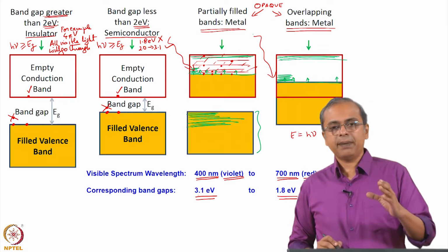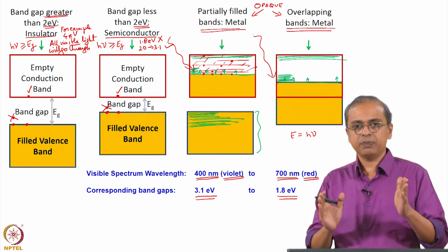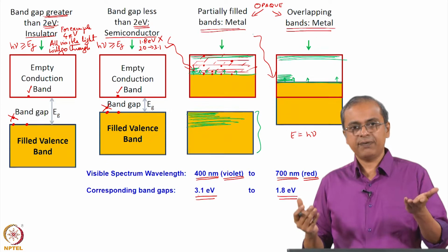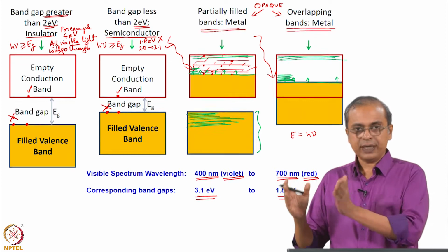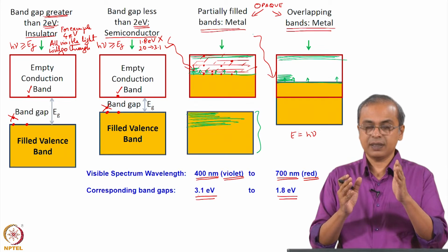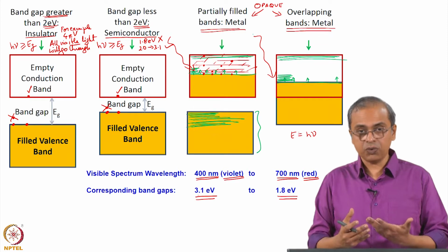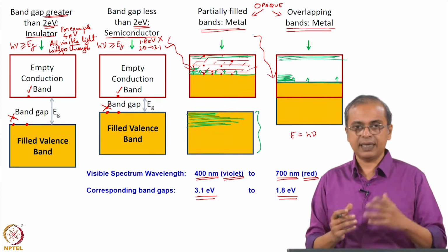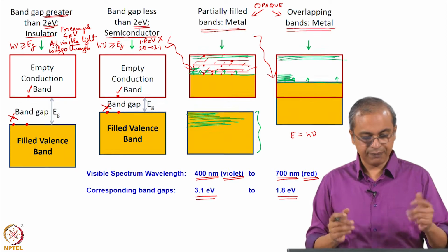Therefore, a sample with a band gap of 4 electron volts is going to be transparent to the visible spectrum. So, insulators, which usually have large band gaps, are typically transparent to visible radiation. And so, based on the band structure you can have an opaque material, a transparent material having some color based on what frequencies are going through and what are not, and another material which is completely transparent, looking like clear glass. That is essentially what we can have.